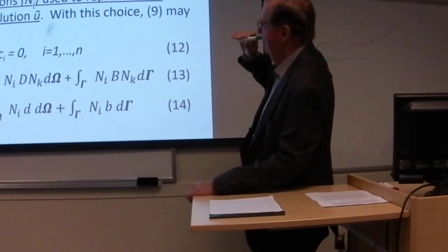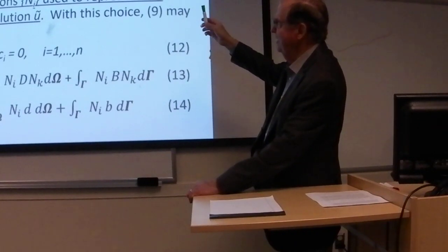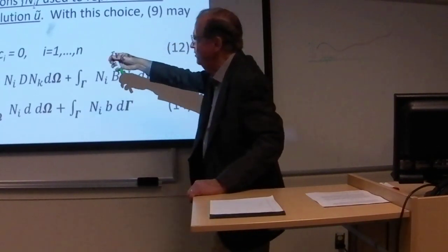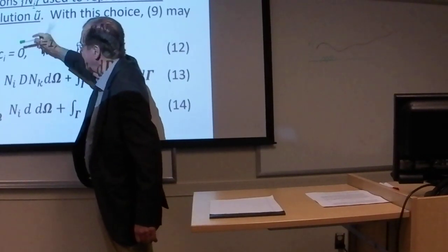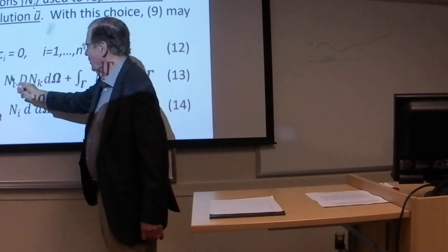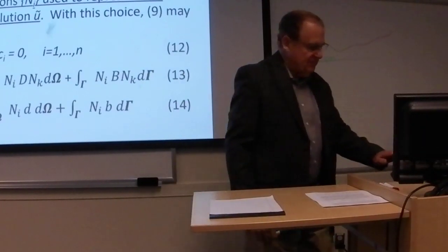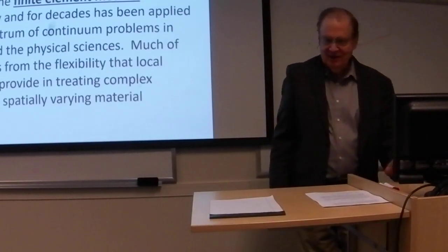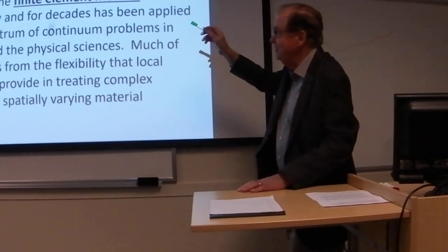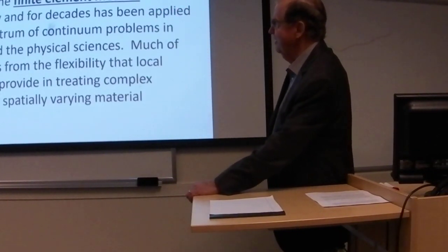So what distinguishes the Galerkin approach from the more general approach we had before is that we use the basis functions for representing our approximate solution U. We use these basis functions as the test functions, as the weighting functions. And so we only have one set of functions in this integral form, or weak form. And then, as I said, we restrict things more and limit our set of functions to these local basis functions. Then the method is referred to as the finite element method.